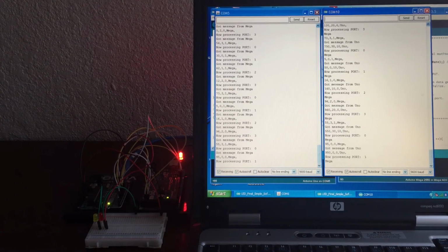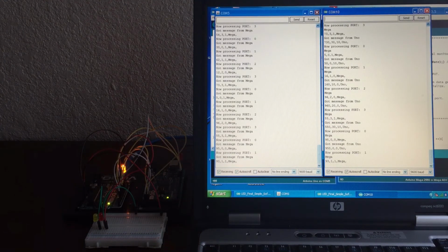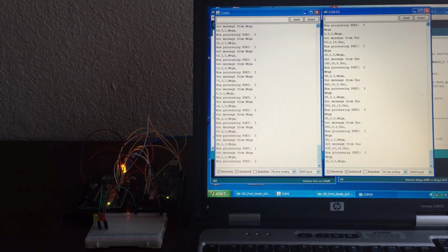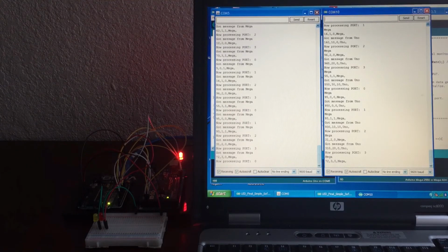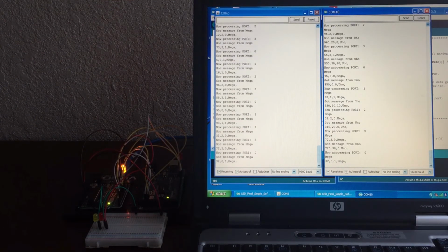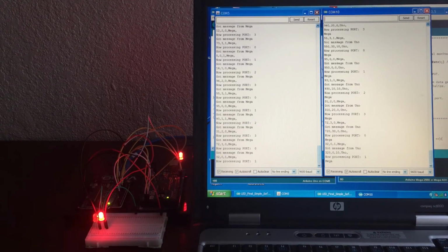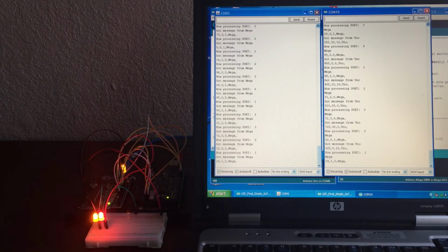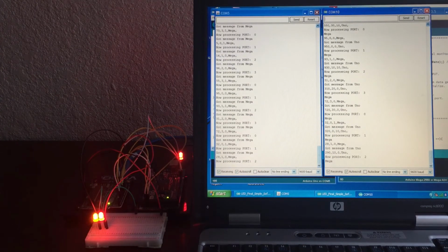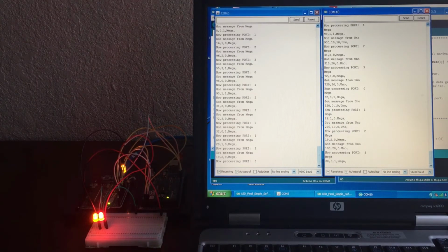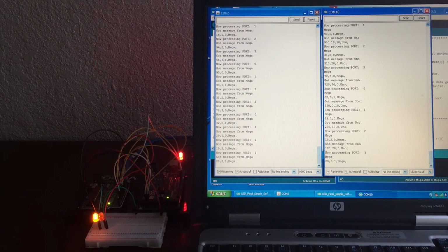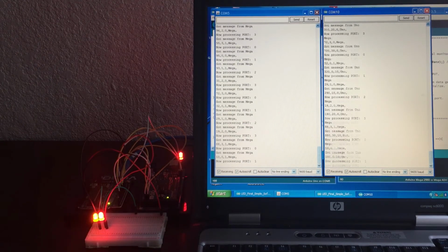Another suggestion would be that you must have 2 while statements, one for the Uno and one for the Mega. This allows timing. If you can, another suggestion would be to use the serial port like an array. You can send some characters and read some of them depending on what you want to do.